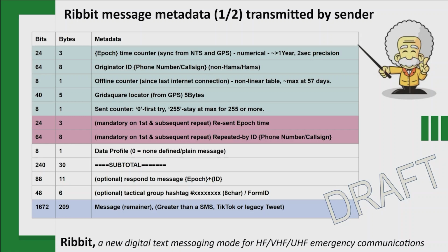We've got the grid square locator. That grid square goes down to 10 characters. I don't know if you've played with the Maidenhead grid square. Usually we go with 6. That's what we include in FT8. When you go to 10, the size of the grid is about the size of a home, which is enough for a first responder to find you with an ambulance. Beyond that, there's no precision needed. I mean, you're like, hey, I'm here. So by cutting that decimal precision, we're able to stay within 5 bytes of data. So that's for location.